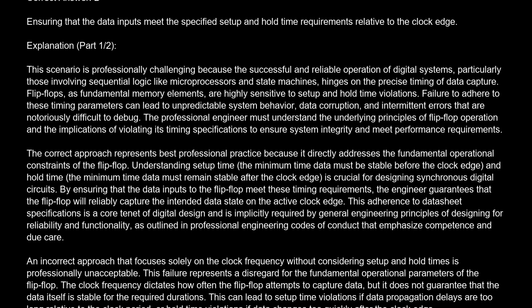The correct approach represents best professional practice because it directly addresses the fundamental operational constraints of the flip-flop. Understanding setup time, the minimum time data must be stable before the clock edge, and hold time, the minimum time data must remain stable after the clock edge, is crucial for designing synchronous digital circuits.